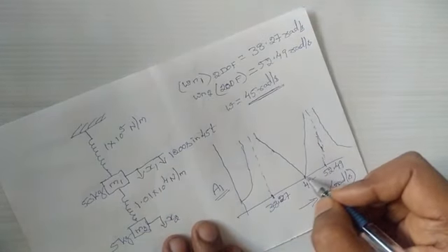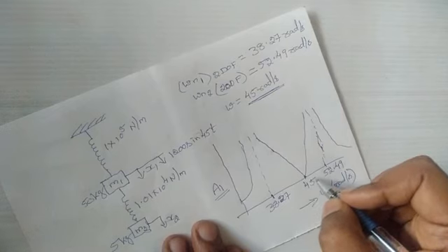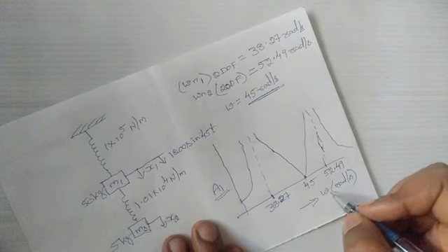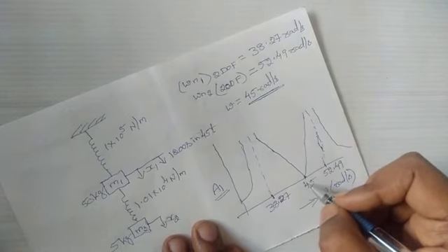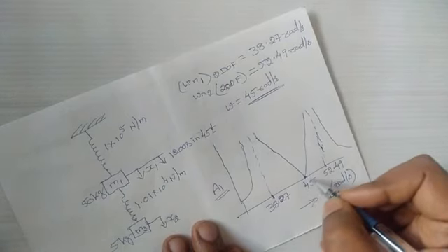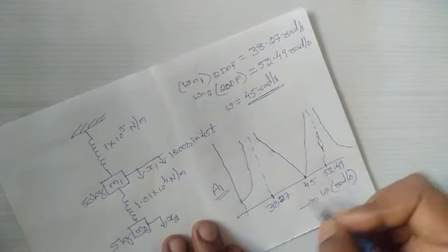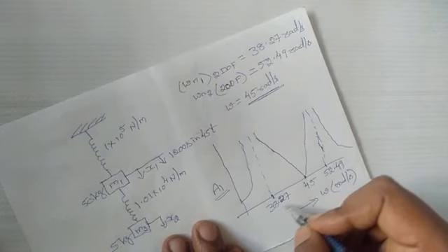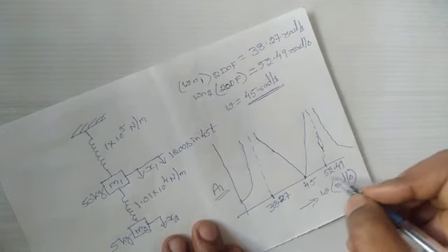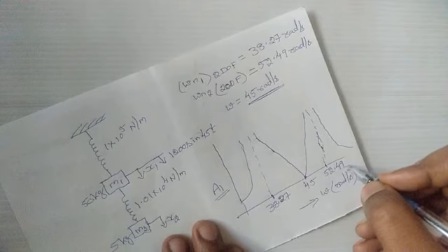So what do we have here? The amplitude of vibration is 0 only when the force frequency of the machine is 45 radians per second. If it is anything other than that, the amplitude is going to increase, and a little closer to this is 38.27, and a little after that is 52.49 radians per second.